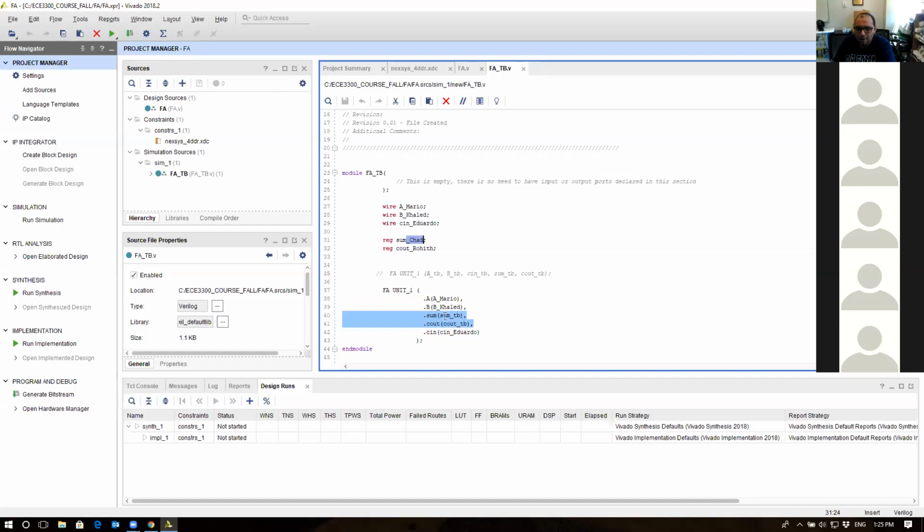Oh, not the module instantiation. I mean, when you declared the wires within the test bench. No, you can declare them in any order you want. It's a parallel language. No, as in the earlier question was, why is it a register and not a wire? Output in general, I put register. Yeah, I'm just saying that if you wanted to, you could flip the wires to become registers.